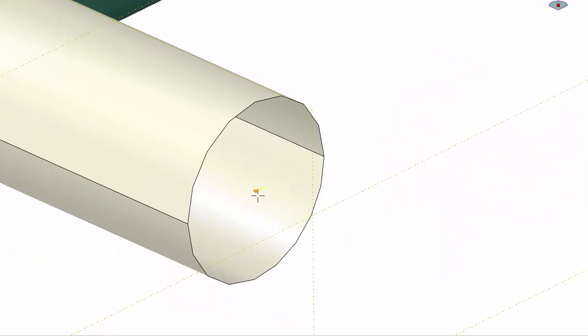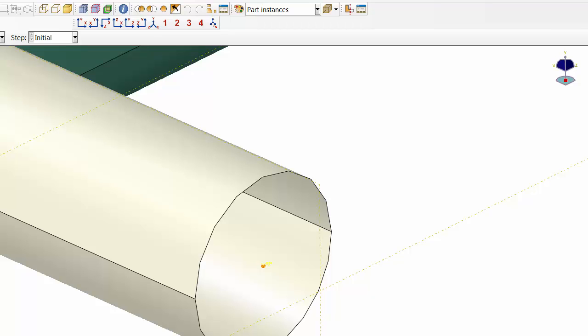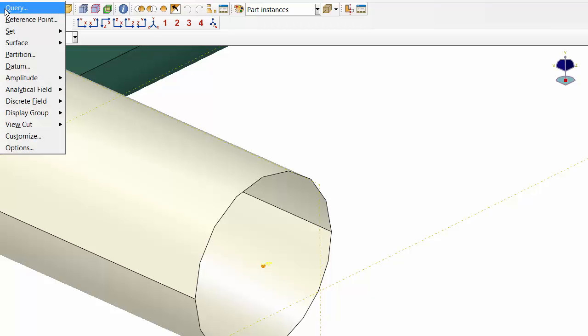This is an important step. So what I'm going to do, I'm going to go to query. Now this is important. I just want to apply a rotational velocity. So if I select this first point and this second point, then I have to put my right hand thumb along this direction. So along this direction, if you keep your thumb and rotate your forefinger about that thumb, that is the direction where the rotational velocity is going to take.